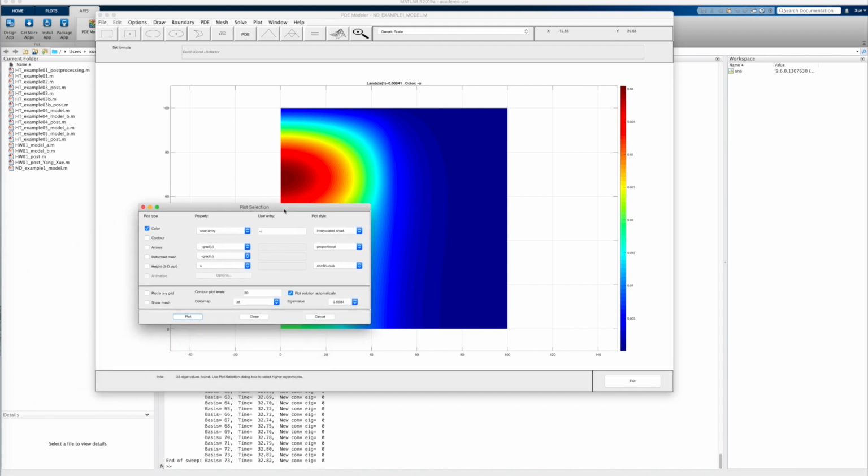So this will meet our expectation. Another thing is that here you can choose different eigenvalues. In this problem, we have found tens of eigenvalues. By default, it will automatically select the lowest one. So this is the one we want, and we don't have to change anything here.